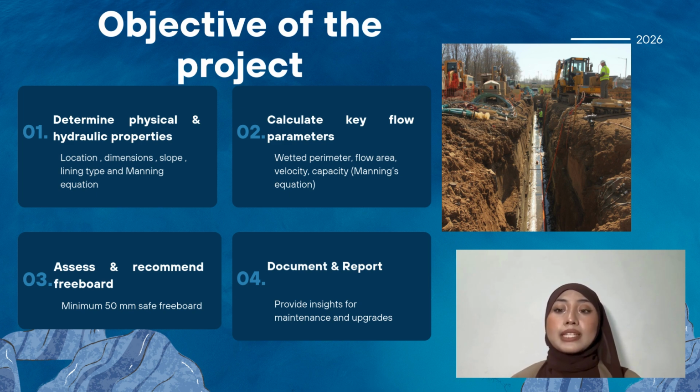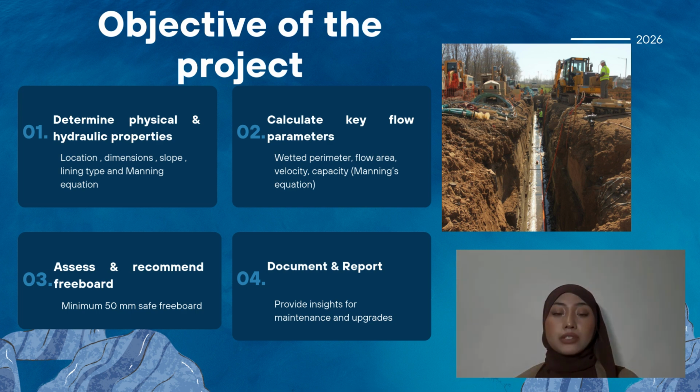Third, we will assess their existing freeboard and recommend a safe freeboard of not less than 50 mm. And the last one, we will document all field data and analysis in a structured technical report to provide actionable insights for drainage maintenance and potential upgrades.